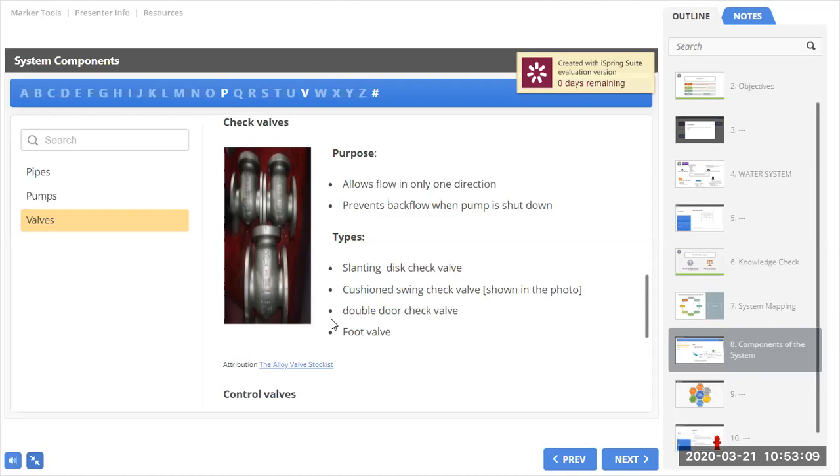Okay, very good, Ezekiel. Ezekiel just made a point that sometimes gate valves are used to regulate flow, which is not recommended. And this causes the lifespan to shorten. Because of that gate that it has, it's not really meant to be used half open, half closed. It's not really meant to do that kind of stuff. So it's better if it's used for just start-stop applications.